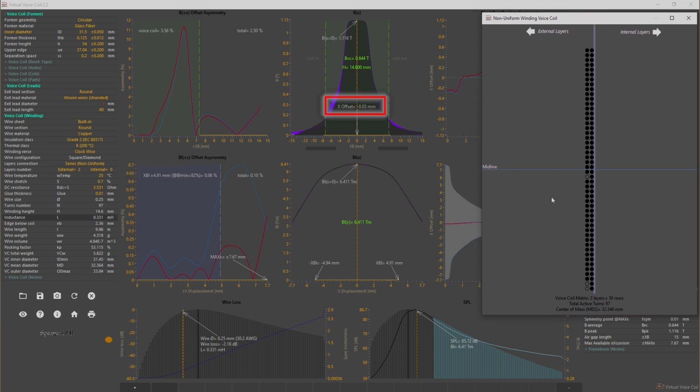One note about the 0.03 mm offset shift. As we know, in some cases, this kind of precision represents a theoretical value for the loudspeaker manufacturing field. Because, except for some kinds of transducers, for example tweeters, compression drivers or microspeakers, mechanical tolerances are bigger, but for those cases, it is convenient to know what value to aim for, or it is useful for selecting one setup or another.